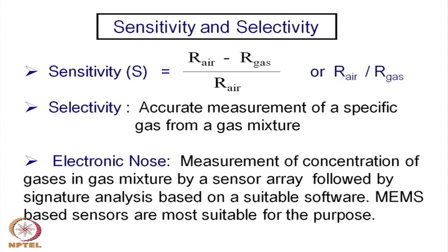To measure the effectiveness, we have 2 or 3 parameters normally used in sensor technology. First of all, the sensitivity. Well, there are 1 or 2 different ways of making a quantitative measurement. This is the resistance initially, the stable resistance in air. So, that is your reference. Normally this resistance is higher than in presence of gas.